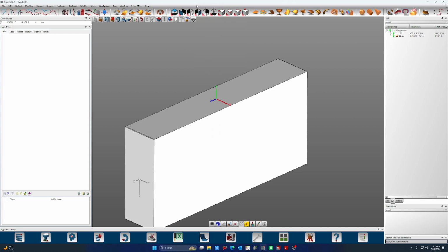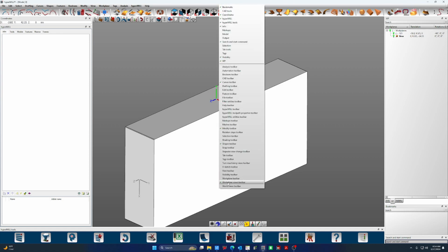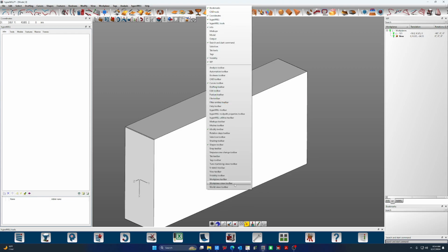And that just becomes useful, almost it gets compounded because you can quickly project geometry from different faces to that work plane. So being able to flip your view around, set that work plane on different surfaces really quickly can help you get the geometry and surfaces where you need without diving into different menus or memorizing a ton of different keys. And lastly, world views.